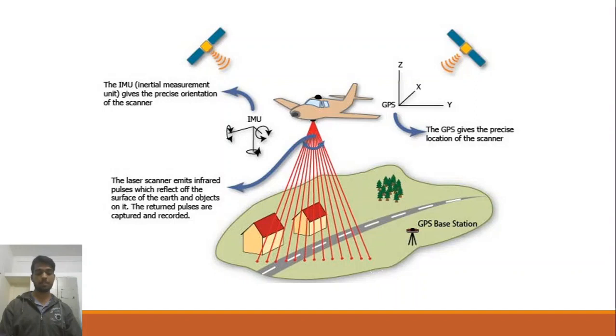The laser instrument fires rapid pulses of light at a surface, some at up to 150,000 pulses per second. A sensor on the instrument measures the amount of time taken for each pulse to reflect back. Light moves at a constant well-known speed, so the LiDAR instrument can calculate the distance between itself and the target with a high accuracy. Like we can see in the picture, there are some houses and trees, and the aeroplane can detect the variation of the topology of the surface. By repeating this in quick progression, the instrument builds up a complex map of the surface it is measuring.